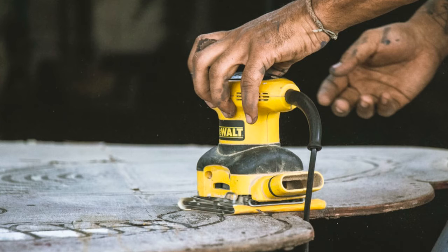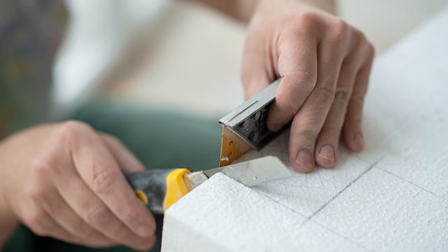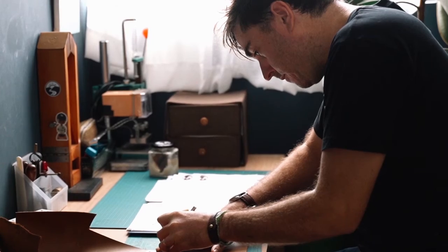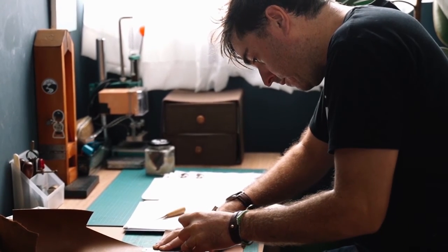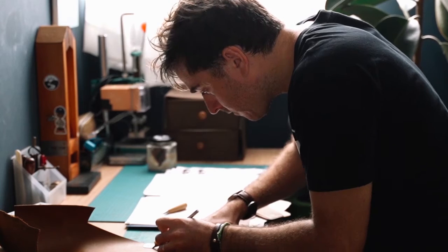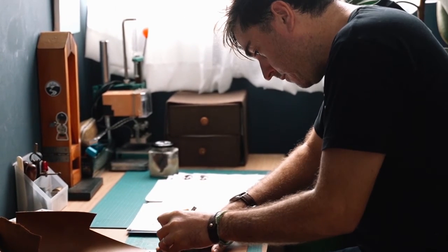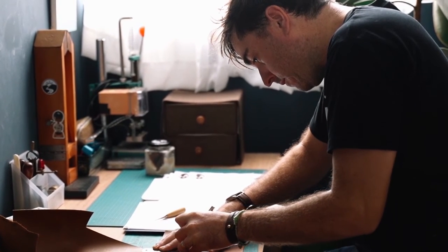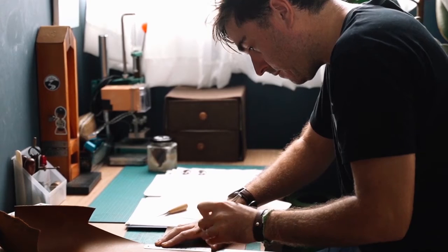Then we should cut the correct size pieces of the chipboard for the base of the seat. By using a router, you will get an accurate and clean cut. The foam should then also be cut to size with a sharp blade. After the foam has been cut, the leather should be precisely measured and cut with a blade to ensure that the covering of the foam would not cause any wrinkles or folds. When measured and cut, the leather is stapled to the chipboard with a piece of foam between the two.